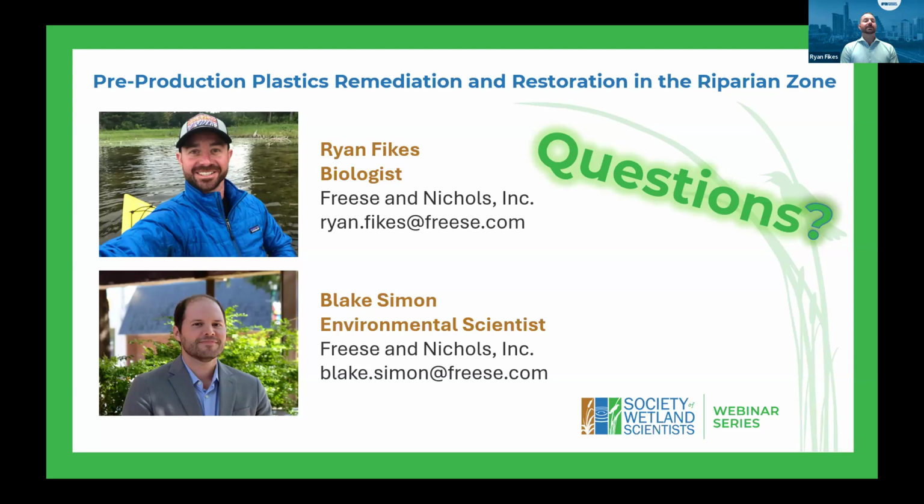Yeah, it will definitely vary based on the size of the plastic. But at the end of the day, it's pretty rudimentary. So we go out, I know Blake was showing some images of this, and you're doing basically different depths of carving out cuts, like a 12-inch by 12-inch by 2-inch deep to identify those nearest the surface. You have a known quantity. You take all those sediments, put them in a bucket of water, make sure you're breaking that all up, dissolve all the sediment so any plastics can release and float to the surface. You quantify those and then extrapolate that to a per cubic foot volume.